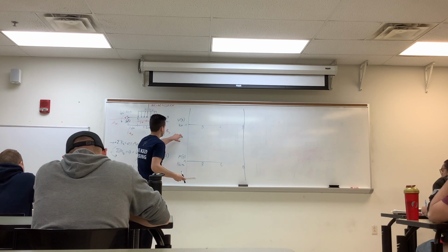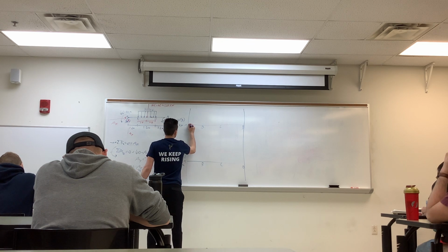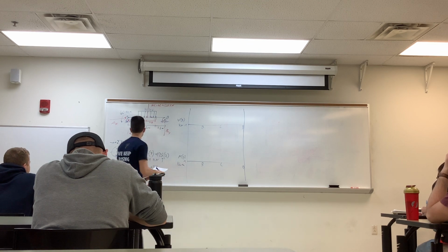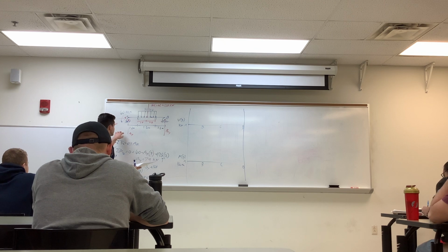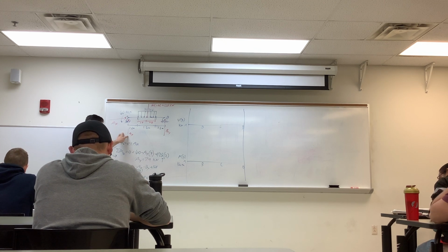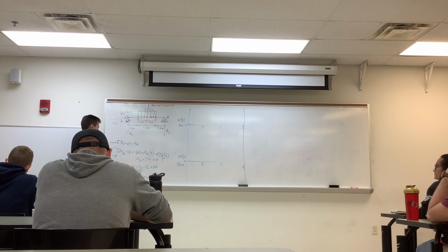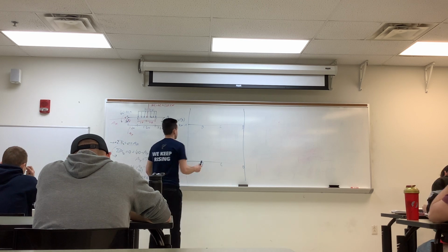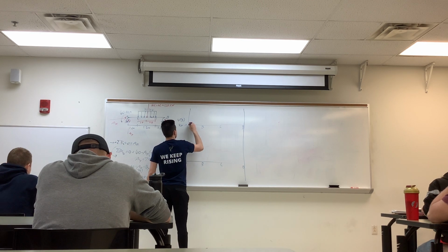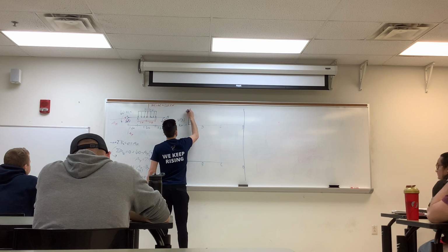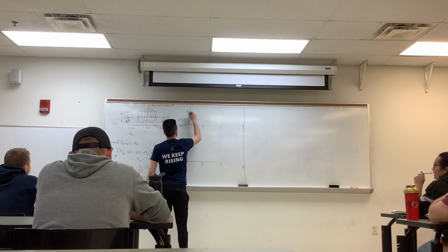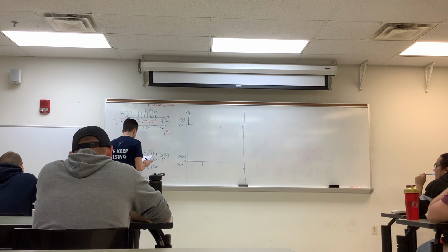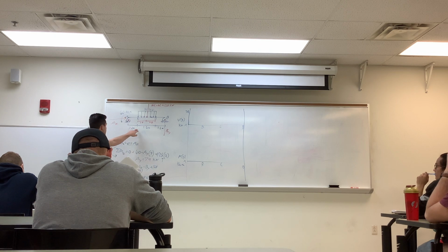Starting off with the shear, everything will start at 0. The only force that causes shear at point A is just this reaction force, A_y. So we'll jump up 79 kilonewtons, so vertical. That is 79. There is no change from point A to point C.